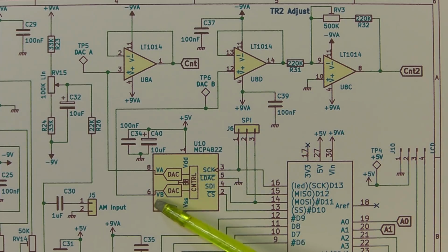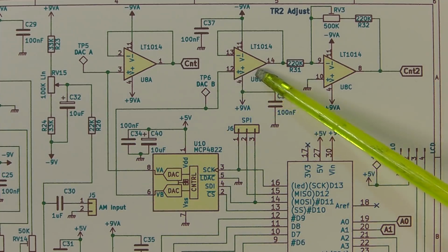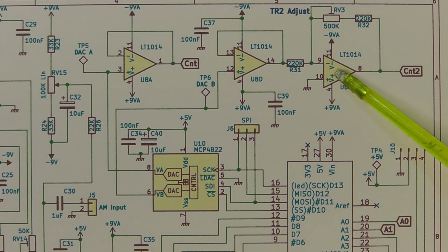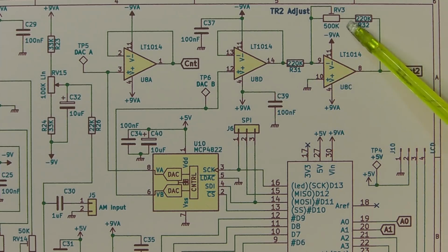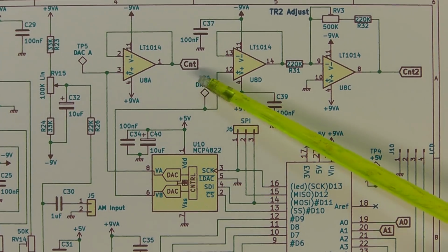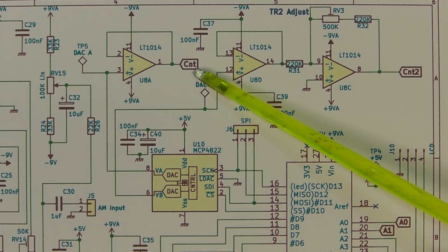You'll also see that pin 6 of the DAC, which we'll use later, is going to a similar buffer and then to an inverting amplifier where we have some gain control, and again that goes to control the timing resistor, but that's for the upgrade later. So let's first of all follow through the output, which is coming from pin 8 of the DAC through the buffer, and goes to a reference point there called CNT.